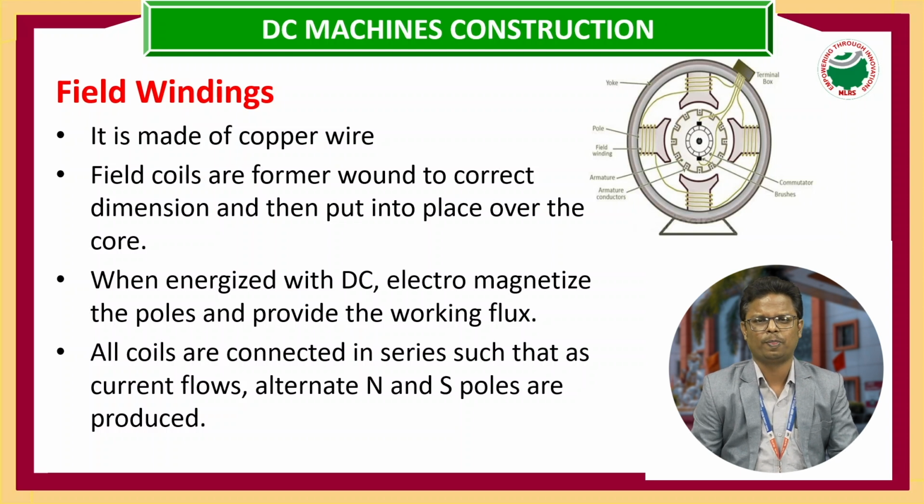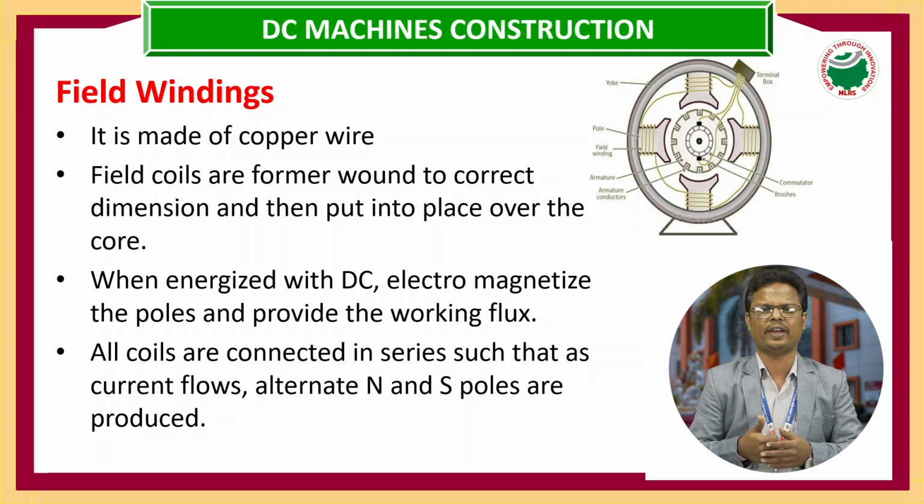It acts as the north pole and the south pole. When we have two consecutive conductors, if they carry the same direction of current, then there is no production of pole. If the consecutive windings carry different directions, then there is a formation of a pole. To identify the pole, we should use the thumb rule. By using the thumb rule, the wrapped fingers can be considered as the magnetic field, and the thumb indicates the direction of the current, or vice versa.